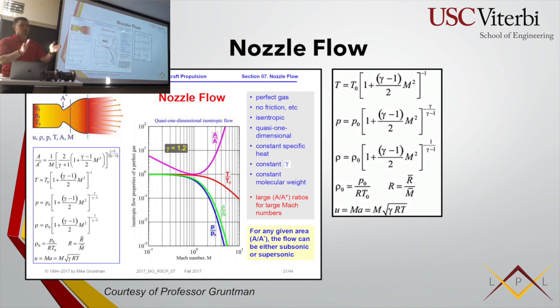So how are you going to put more material and take material off? Things need to be moving. People don't do it because it's not easy, I assume. But that's why it's not done. Yeah, and that's what an Aerospike is. I can show at the end a video of the Aerospike, but the concept is it's like a bell-shaped nozzle, but it's backwards. It's inverted. And so at your exit, it ends up creating a layer where P always equals PA, and so you get the most efficiency.